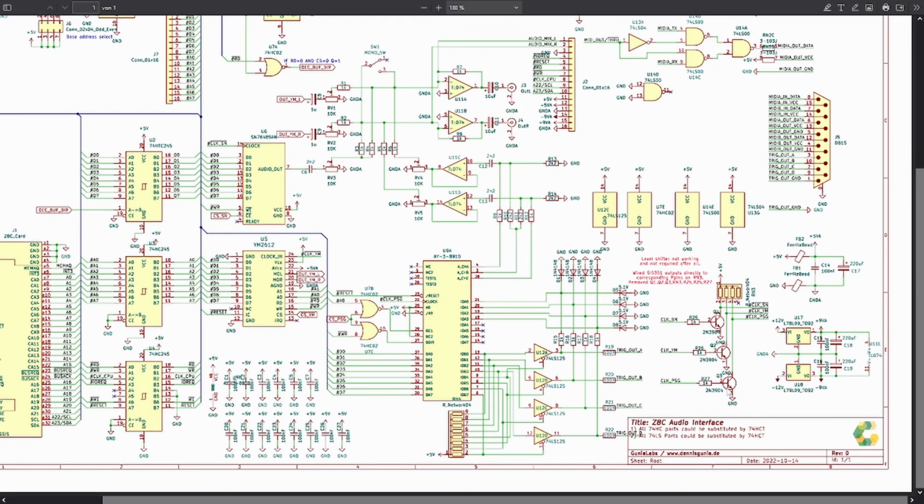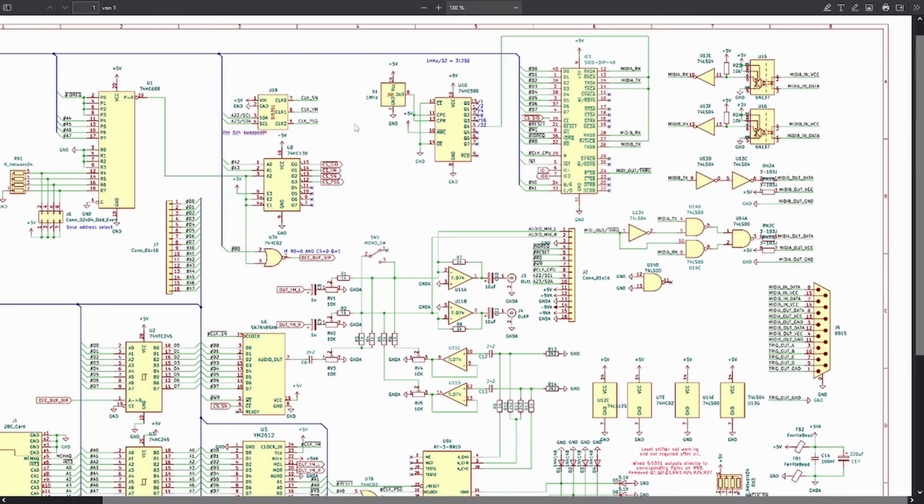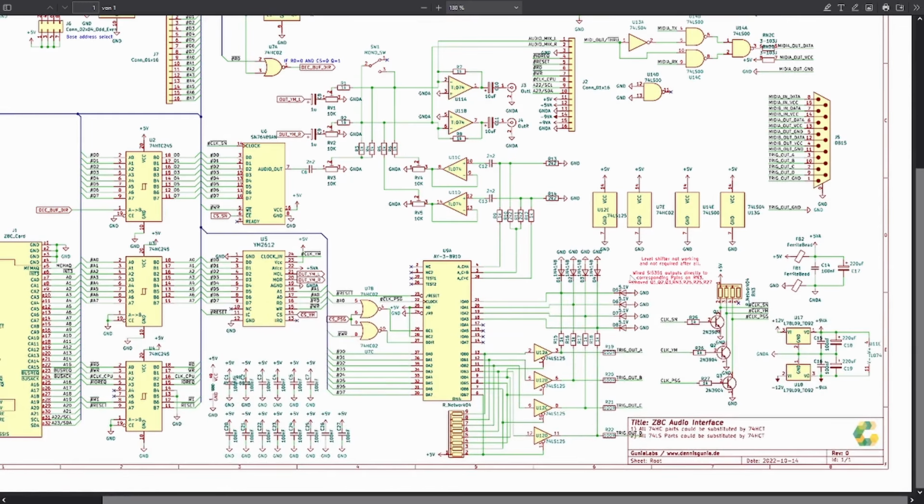There are some circuits on the internet which I already found which are using those outputs from the SI5351 directly, because 0 volts to 3.3 volts is still enough for TTL logic levels, or at least I read that. And yeah, we will see in the next part.